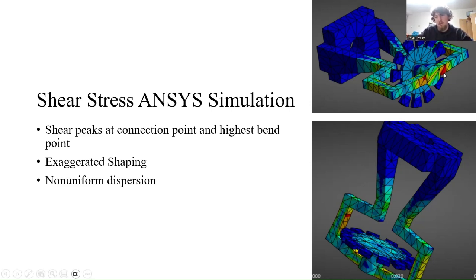And it's concentrated there because that's where the sharp edges of something coming down and the flanges which are held on that upward support meet. So you get that shear on these bottom sides. And on the bottom right side, you get that shear that's a result of something being bent. And so you get that separation, and that ends up with a high concentration of shear there. Again, these are exaggerated shapes to visualize what's happening, but it's a pretty good approximation of what to look out for in the design and the forces that are coming down and pulling it back up.